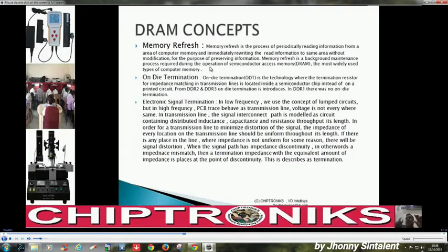That is, the RAM is powered on and RAM refresh has to be done because the context is saved in RAM. What do you mean by context? Context means when we power on the notebook motherboard from S3 state, it will resume at the same place from where everything is starting. That is, no data loss in the RAM in S3 state, right?